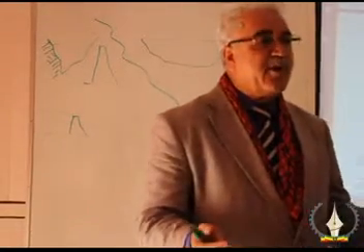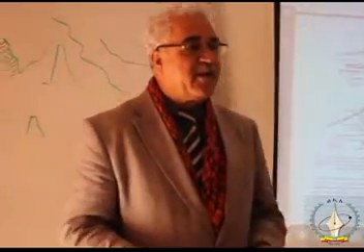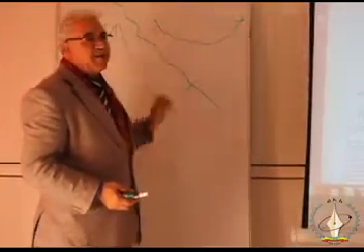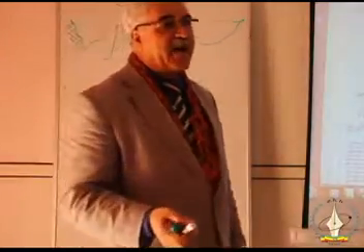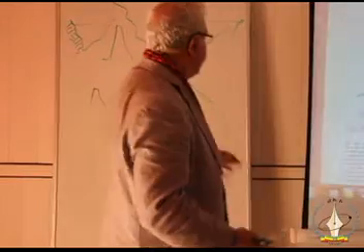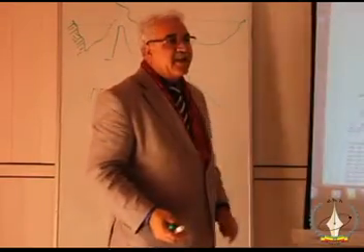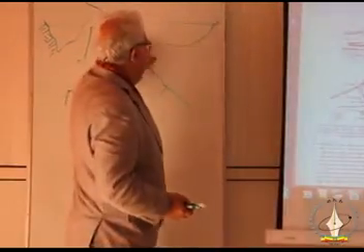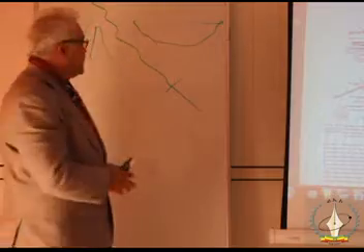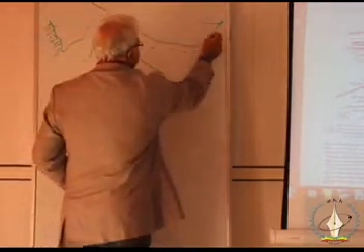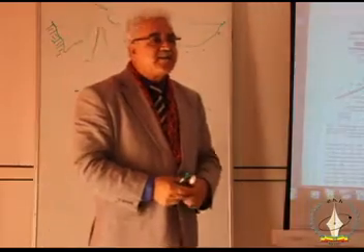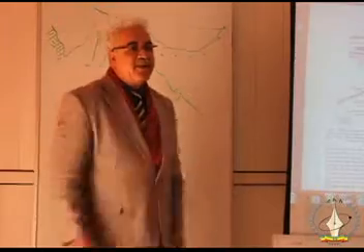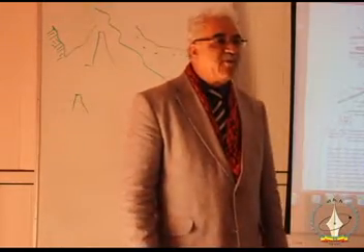You should look for an earth dam, a rock-filled dam, or an earth-filled dam, because normally it is a good idea that the type of material that you select for building the dam matches the natural material at the bottom and the banks of the river. Because if you design a concrete dam here, the water may seep through at the bottom, and then the concrete dam will not be worth anything. Underneath it will be eroded, and the whole concrete dam will collapse.